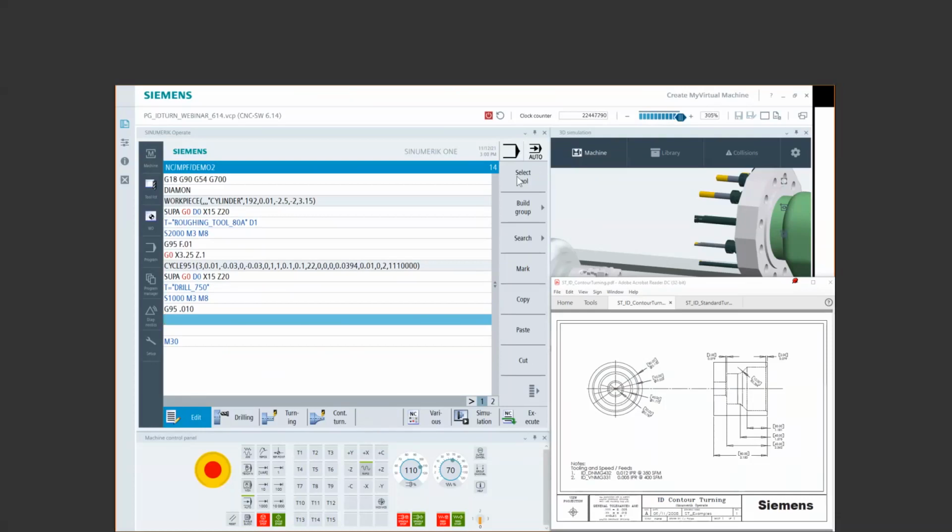You must pre-position the drill on center line of the spindle. In ShopTurn, it does it automatically because you have this whole centric drilling series of cycles. In G-code, it's the same cycles whether you have live tooling or not. So we're leaving it up to you to pre-position the drill. So you have to tell this thing to go to X0, or if it's an insert drill, you can do a little bit of an offset, right? Insert drills do allow you to drill not right on 0.